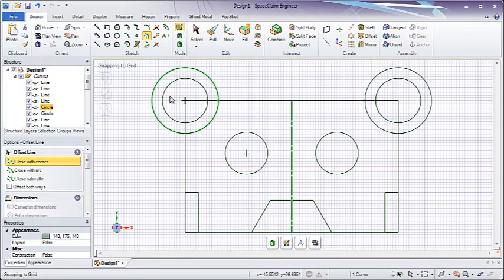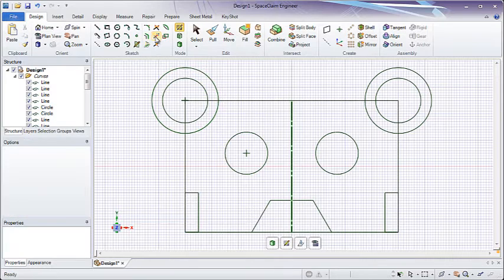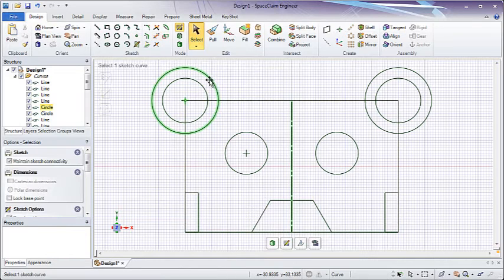The last thing I'll do is use trim. Trim is located on the right of that group, and the shortcut is T for trim. When hovering over lines, you'll notice lines are automatically segmented into shorter sections. This is what it looks like with the trim tool on versus regular select.